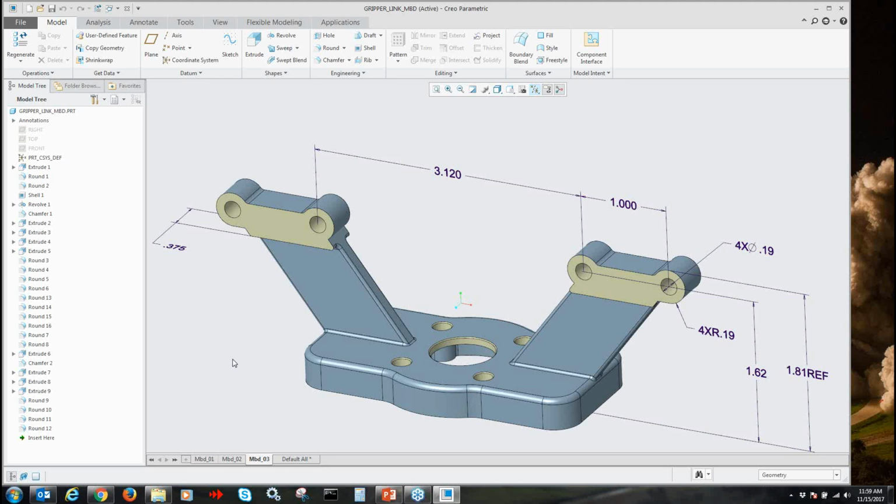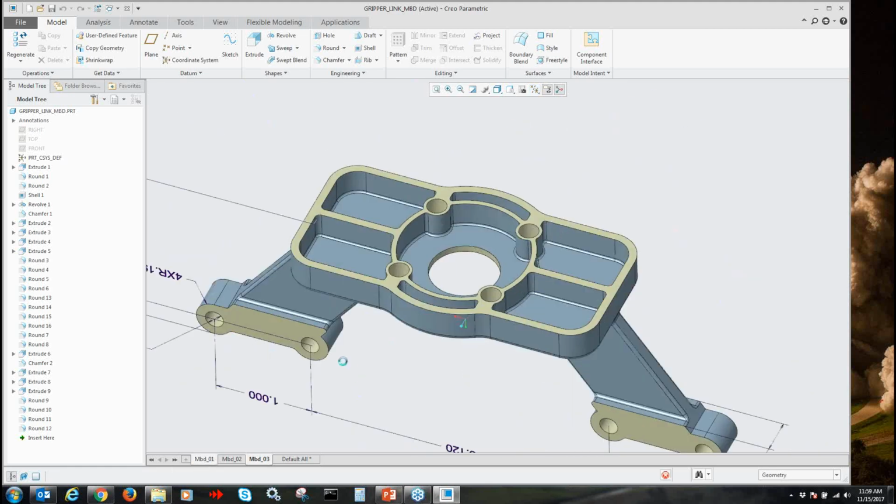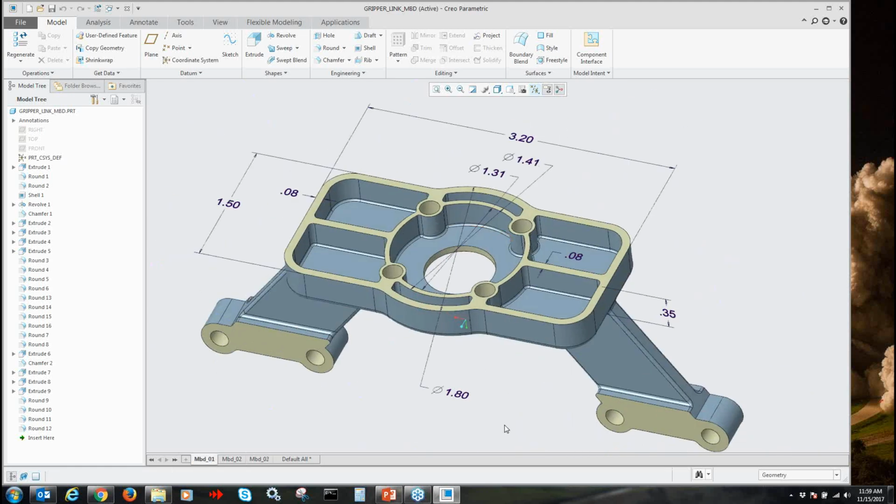It highlights the dimensioning schemes that are on the drawing for me that I want represented in that view orientation, and any of my tolerances that I may have, any text with my notes. You can see this one here. We've got some dimensions and everything else. So I'm going to go ahead and add some items into this. I'm going to start off here. I've got my MVD 01 view that I've now set.